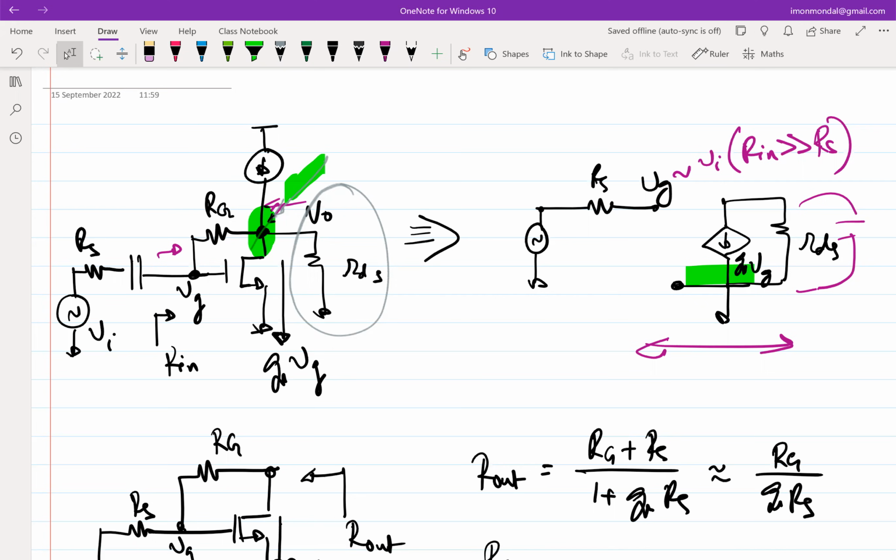So that's what we will do, and that's what we are doing all through. An approximation of KCL is that you figure out the lowest impedance path and ignore everything else. Which means you have to have the ability to look at the circuit and figure out the impedance at different nodes, right? So that's what I did. Even what I did here is an approximation. This is not exactly how it will function, but it will give you an estimate of what the circuit parameters need to be.